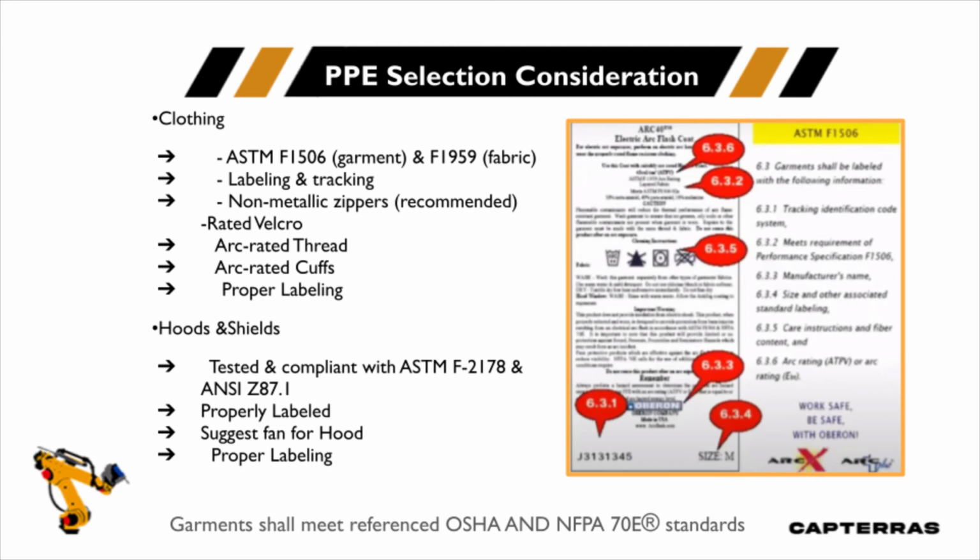But all I do want to do is make sure whoever you work with is a reputable manufacturer whose test reports you can actually see, especially if you get into the arc flash suits. I want to see copies of the test reports indicating that this garment complies with the ASTM requirements. So please pay attention to who you're using and what garments you're picking here, because there is a difference. We have seen garments coming in from some locations, some countries, that just were not providing a level of protection. We threw them into an arc testing laboratory, and they were not functioning properly. So it's very important we pay attention to this.